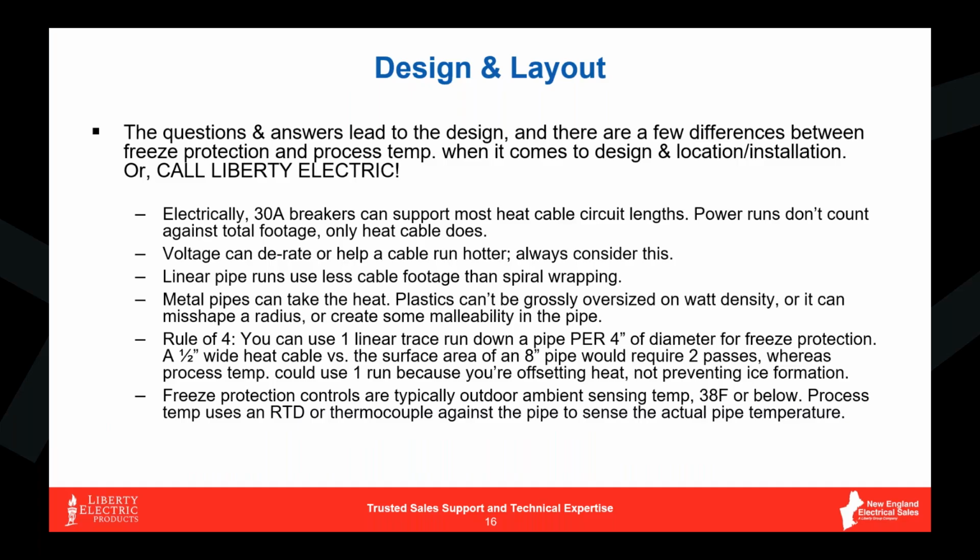And consider, again, what's in it. Is this a pressurized process system? Or is it going to be a freeze protection system where all your fluid is going to be in the lower half of the pipe? Gravity is going to pull that fluid to the lower half. So linear runs 99.9% of the time are better than spiral wrapping. Again, we talked about metal pipes being able to take all the heat. Plastic pipes can't so much.